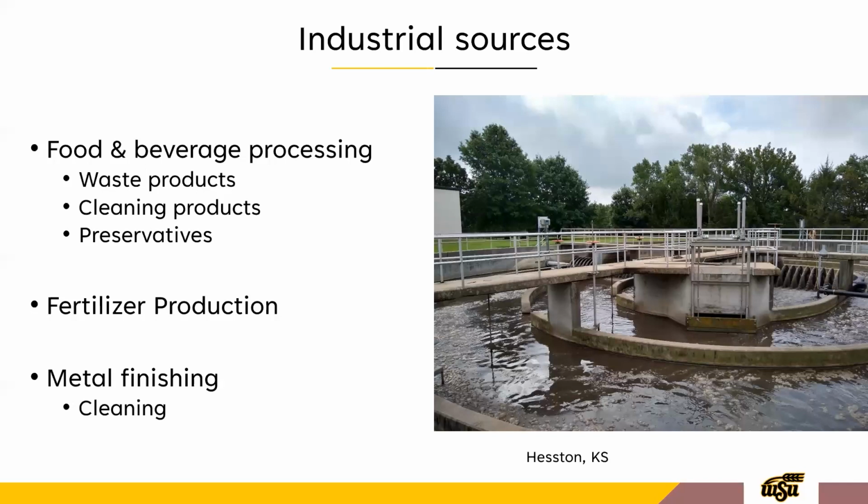I think that smaller communities with industrial sources certainly may need to have more data to understand what's going on than the monthly grab samples that many facilities have. A monthly grab sample could be representative, or it could be very, very far from your typical phosphorus level, especially if there's some sort of batch discharge going on.